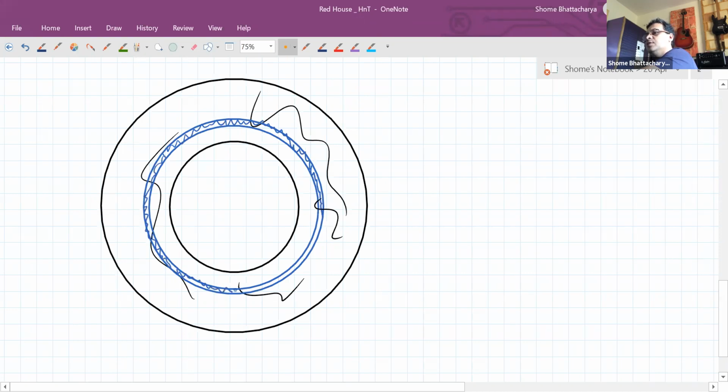And as we go from shell to shell, that radius varies from A to B. So this shell itself has radius r, and it has a differential thickness of dr. Okay. Now remember, the heat is cutting across radially like this. So the heat current is encountering a surface area, or a cross-sectional area, of 4 pi r square, and it is going through a length of dr.